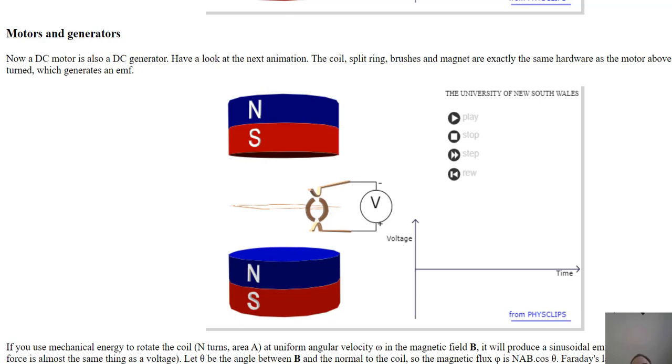If the electrical energy is rotating the wire and making mechanical energy, well, now it's a motor. So for instance, if you took a house fan, unplugged it, and plugged a voltmeter into the 2 prongs of the power cord, and you turn the fan yourself, you would see voltage generated at the prongs of the plug. So motors and generators are the same device, just they're used differently.